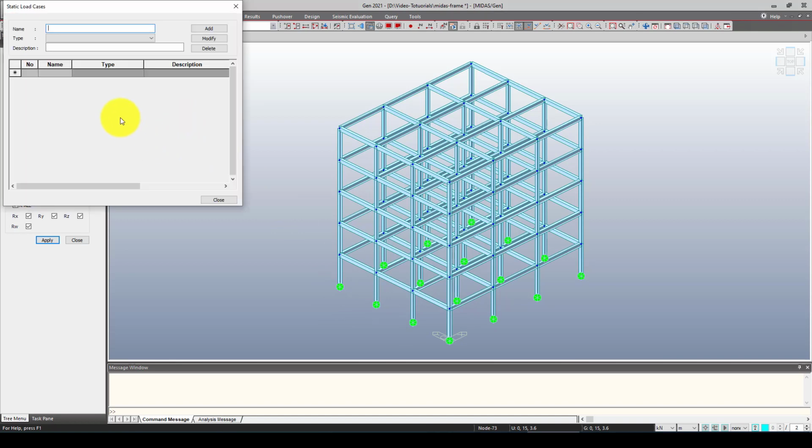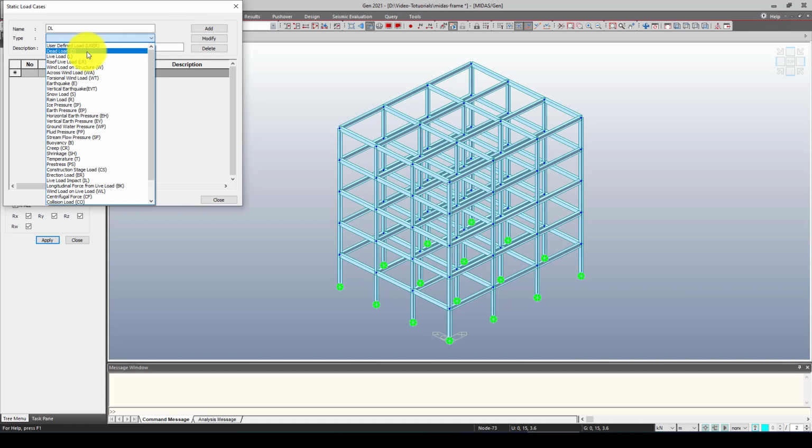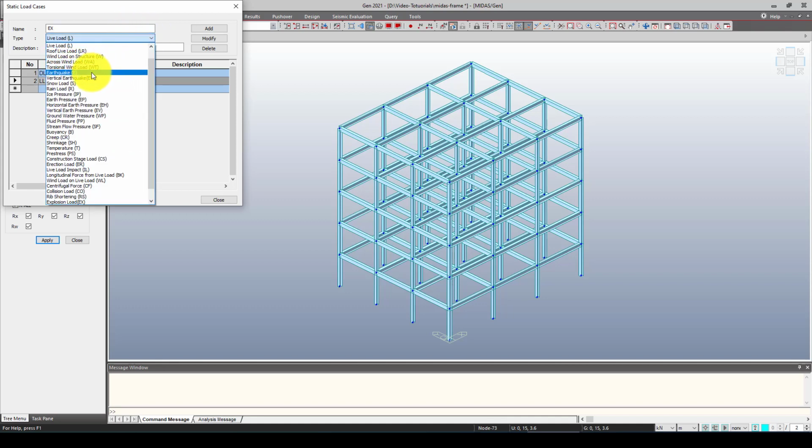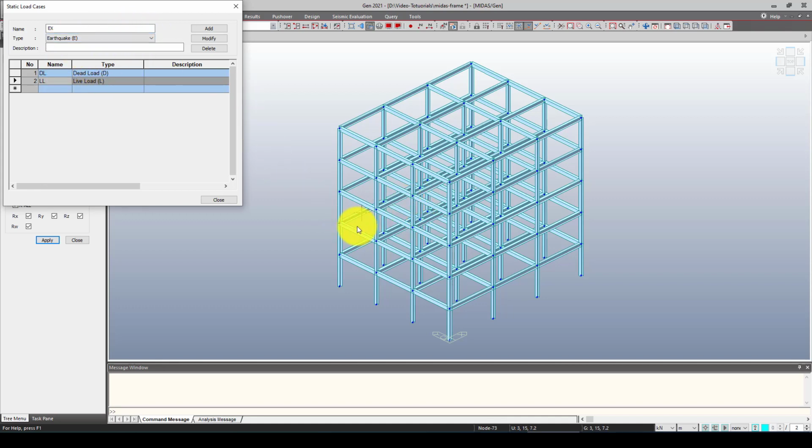Next I want to define loads. We have a dead load, which includes the self load, and a live load, which is the floor load, and also the seismic load. I can consider two directions, because in one direction the structure is stiffer and in the other it is less stiff, so x and also adding y.